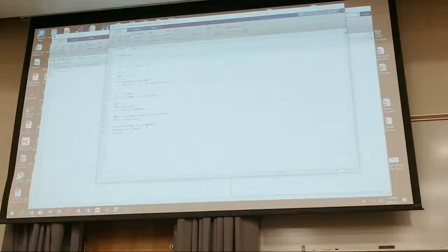A lot of this will just fly by you. You won't appreciate it until you have to use it. Whenever you're plotting in MATLAB, you always put the horizontal variable first, it's omega, and then the vertical variable. I'm taking the absolute value of the actual Fourier transform, xf. This is this one right here. Then I have to put a comma.